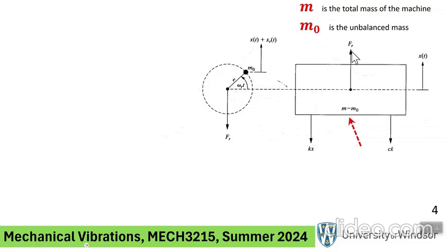And because it's an internal force, when you look at the rotating component itself, there is an equal and opposite value for FR, which is acting on the rotating component. Therefore, the free body diagram of the rotating component is drawn with FR here, and that's pretty much it. There is no other external force acting on this. Now remember, we are assuming that things are measured at the equilibrium configuration, therefore we don't have to worry about gravity, okay?